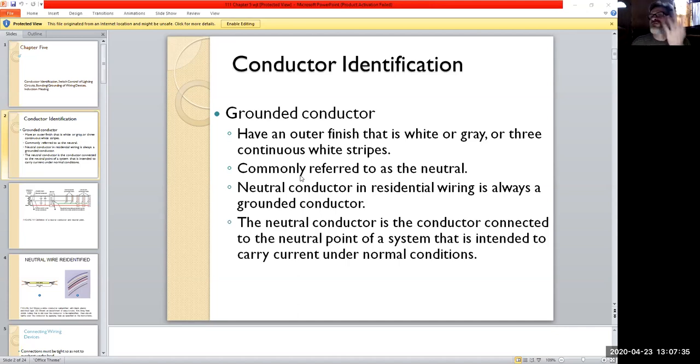And this is where you got your colored electrician's tape. Usually I ran around with, you always have black. Black is a good one, right? Because that's just for taping everything up, your wire connectors and that kind of thing. I always did a tape wrap around every device.